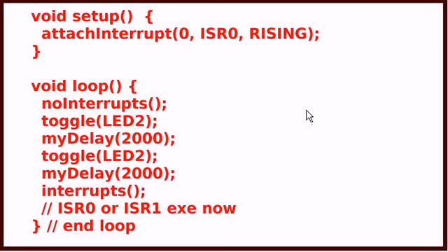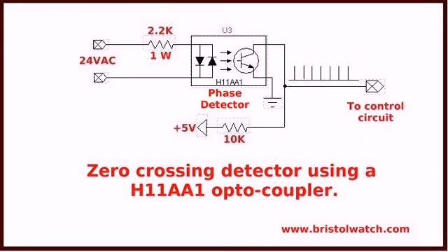You would want to use this if you've got some really particularly tricky timing that you do not want anything else messing with. So remember, if you use NoInterrupts, all the interrupts hardware types, including delay and some other functions, no longer work, and you will have to write your own delay routines.